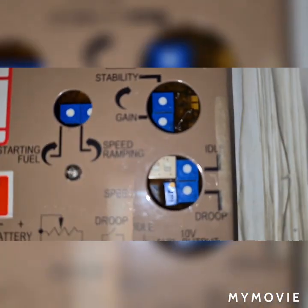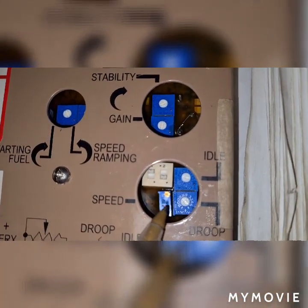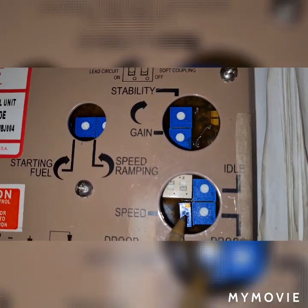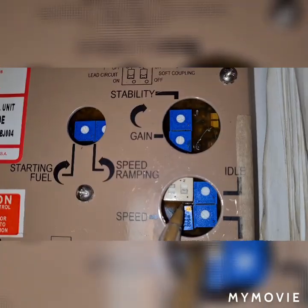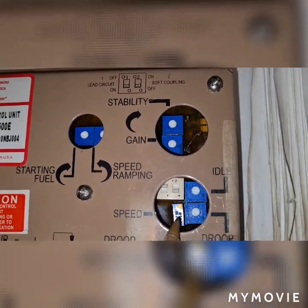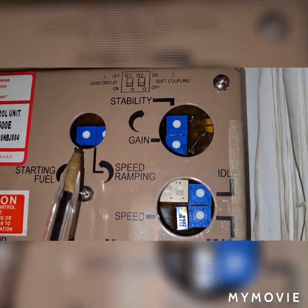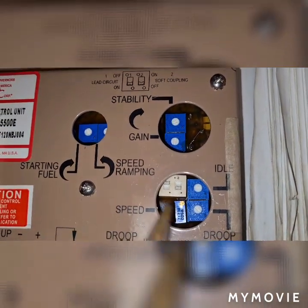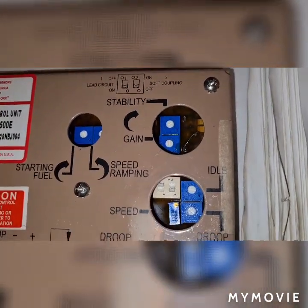Then we adjusted the RPM a little bit. We adjusted the speed from 1865 RPM to 1810 RPM, and we set the starting fuel set point pointed at 3, and we also set the ramping speed between 3 and 8. In doing this, while the engine is without load, we are able to parallel the generator with our running generator.